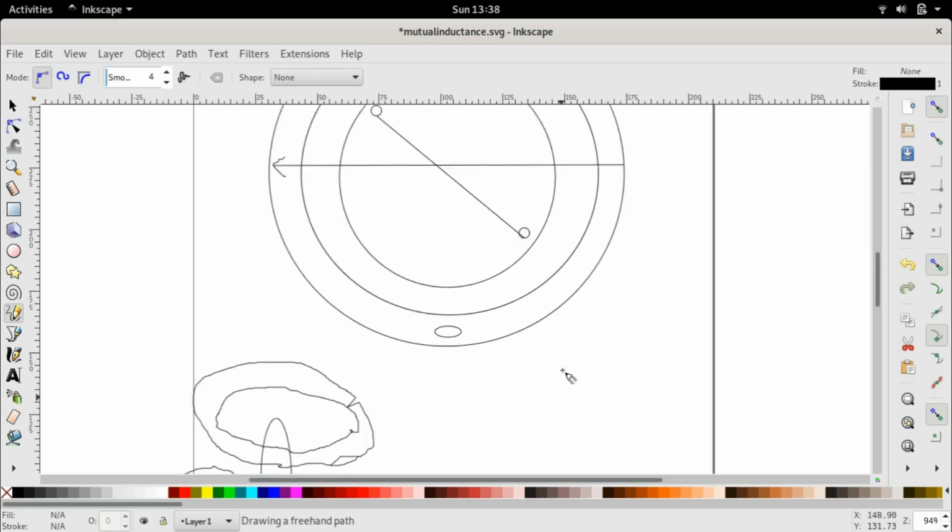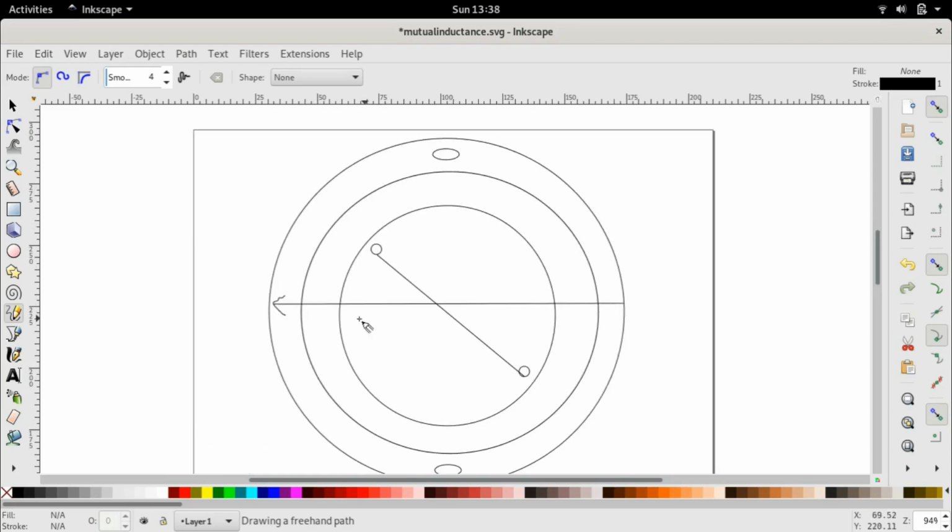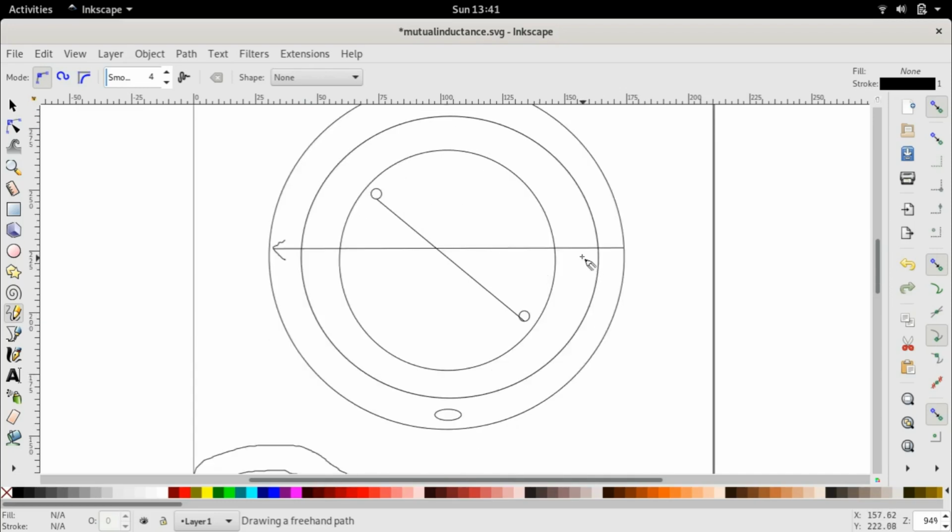And since the stator is not rotating, this flux is in this direction, but because an AC current is flowing in the stator, this flux will change from a 0 value to a positive value, back to 0 again, to a negative maximum and back to 0. This is how it is if there is an AC current flowing in the coil. And therefore, this AC flux will also follow the same AC path.